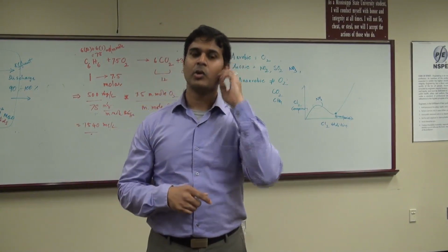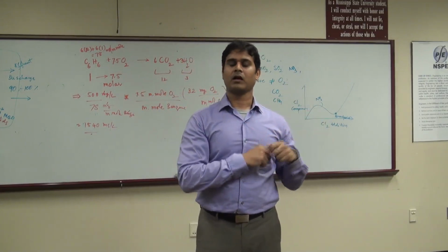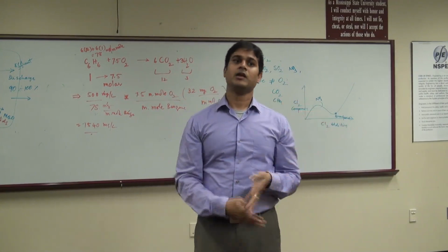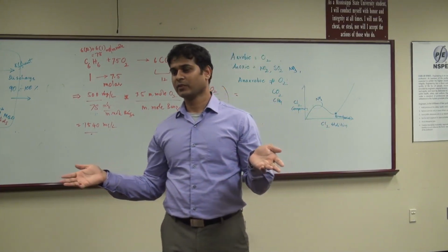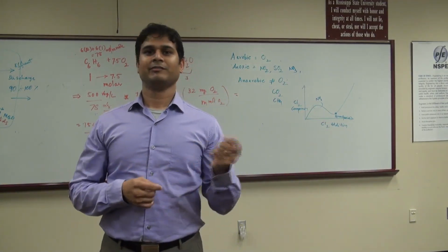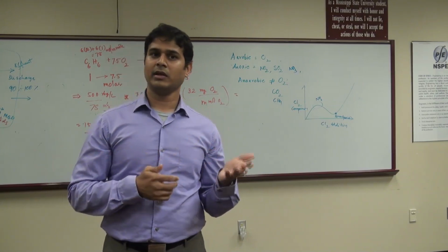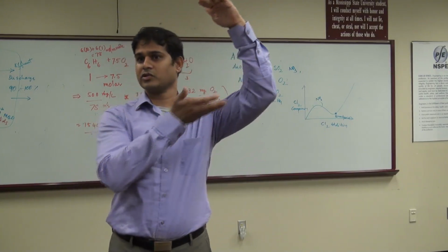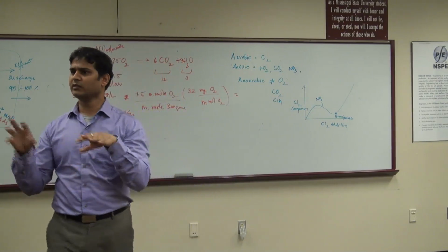It's asking which pollutant in that water quality has been reduced the maximum. It has been removed like 5 log removals, in our language at least 4 log removals. So that's the highest. pH may change by a few units, but in percentage it's not big. And BOD is 90% or 95%. But when you look at what you're starting with and ending with, that's what the question is about. Did you follow the logic there?